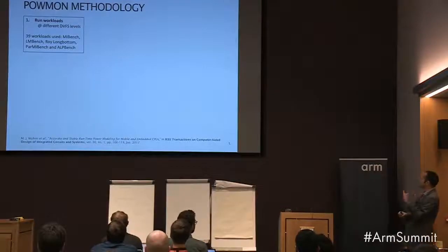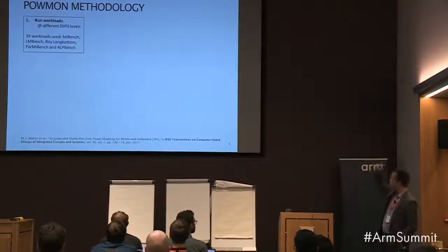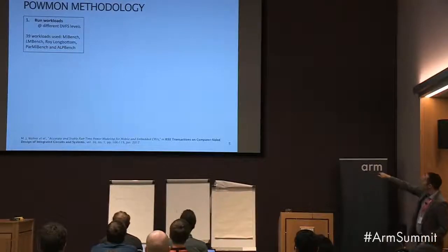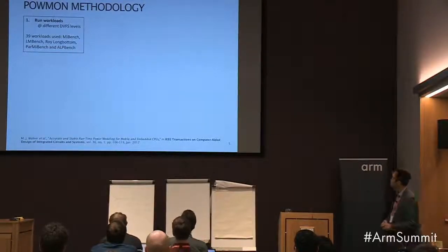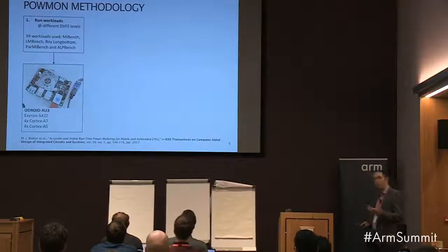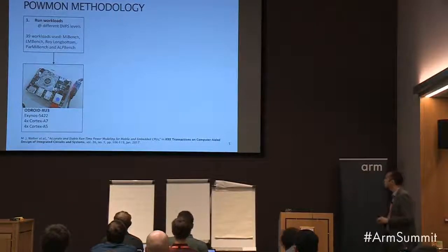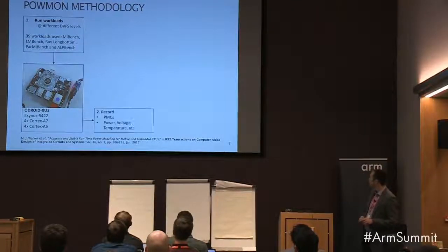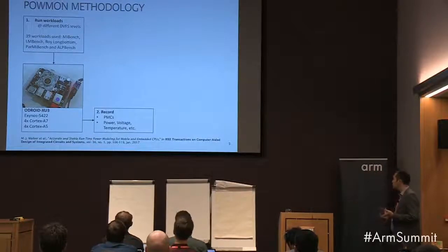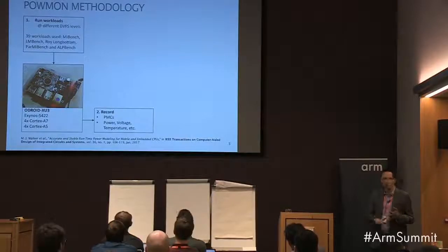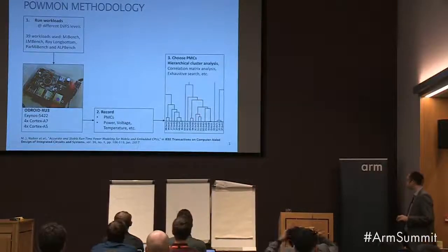So the power modeling methodology that we came up with is titled PMC-based power modelling (PowerMon). So you start by running a set of workloads on your system. You run them on a practical embedded device. Lots of the work that we've done so far has been on one of the Odroid boards, which contains the quad-core, the octa-core big.LITTLE device. From that, we record a range of statistics, so performance counters, and then also things like power sensors, voltage sensors, temperature sensors, and so on.